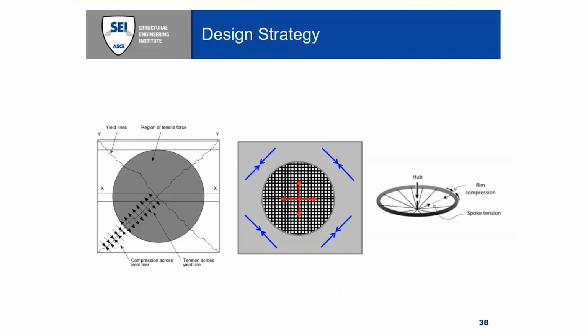In this case, the spokes are analogous to enhanced reinforcement in the slab, so upgrading the welded wire fabric that's already there for service. And the rim is analogous to the periphery concrete, which conveniently, as structural engineers, we always over-design because we want a tensile failure mode. However, all other floor members and columns would require protective insulation in order to support the edges of our bicycle wheel, keep it elevated in space.